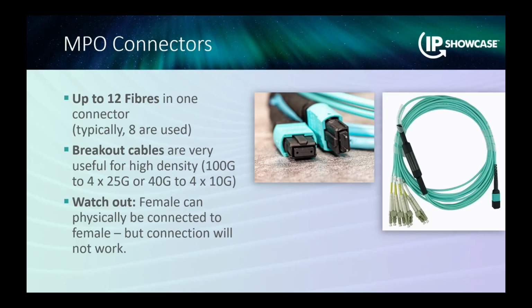And it's actually possible, unlike other connectors we know, to plug a female connector into a female receptacle. And so this does physically work, but it does not optically really work very well. If you're lucky, it doesn't work at all, because then you're immediately suspecting something. If you're unlucky, then it does work halfway, and then you think it works, but later discover, no, it doesn't. So that's something to look out for in the installation. Usually installation is, I mean, that's the thing we have under control, but that's a thing a colleague of mine stumbled on in one of the projects.